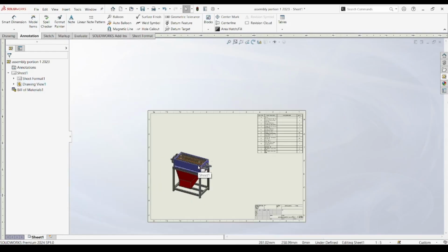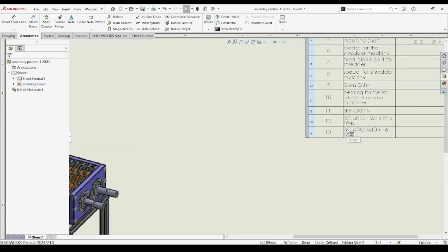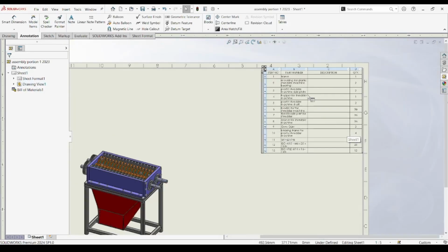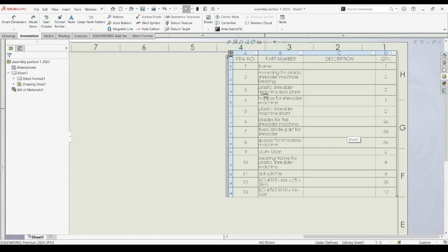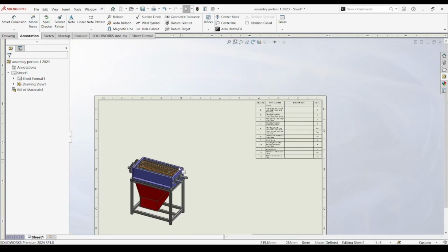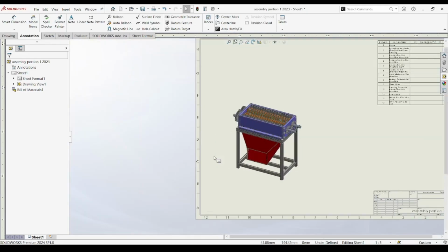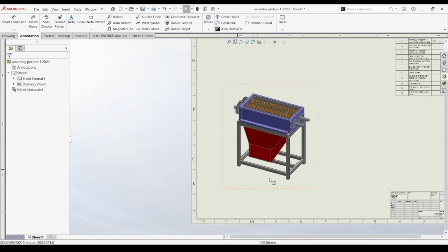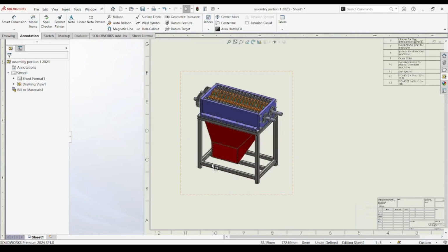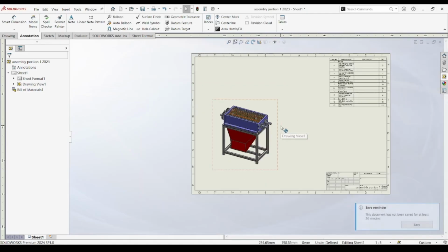We also discuss how to handle common issues, like duplicate parts, missing descriptions, or incorrect quantities. SolidWorks automatically counts instances of a component, but if an assembly has flexible or mirrored configurations, double-checking is key. Miscounts in fasteners, spacers, or bearings can lead to headaches during the physical build.